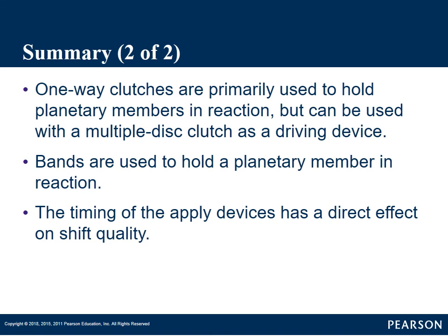We're going to look at how to diagnose the hydraulic system by checking pressures, and we're also going to look at clutch and band charts, so that if we have a transmission not shifting correctly or not shifting into certain gears, we can look at a clutch and band apply chart to see what clutch is supposed to be holding, what band is, what solenoids are supposed to be operating, and so forth.